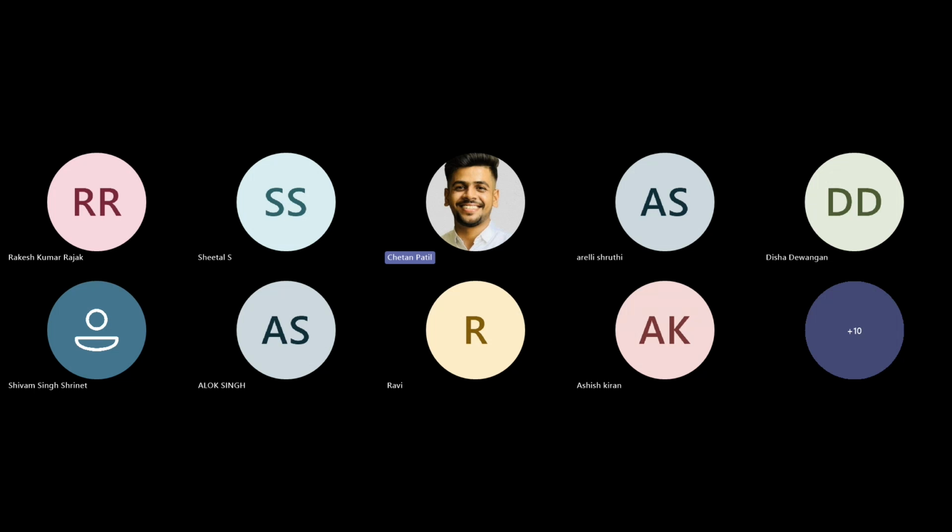So this particular thing defines that rotation about the Z direction is the only free motion with respect to the type of joint you are using. But motion can also be generated in X and Z directions, and in rotation about X and Y as well. So this defines that the redundancy is due to other joints that you have created with reference to this joint.